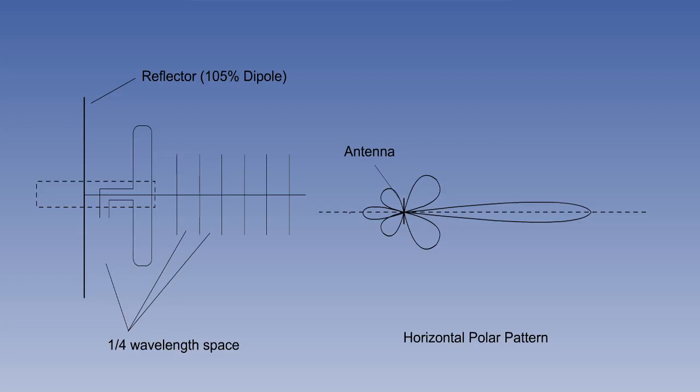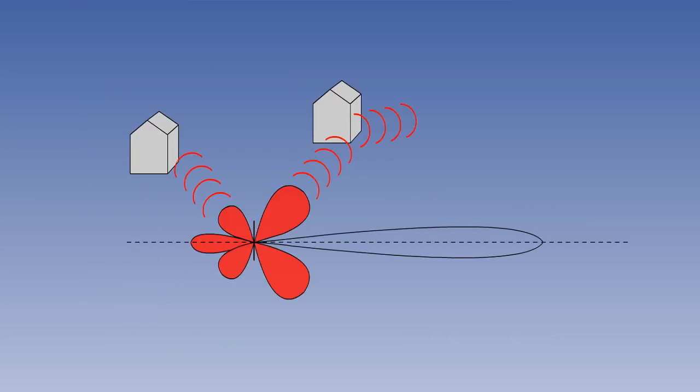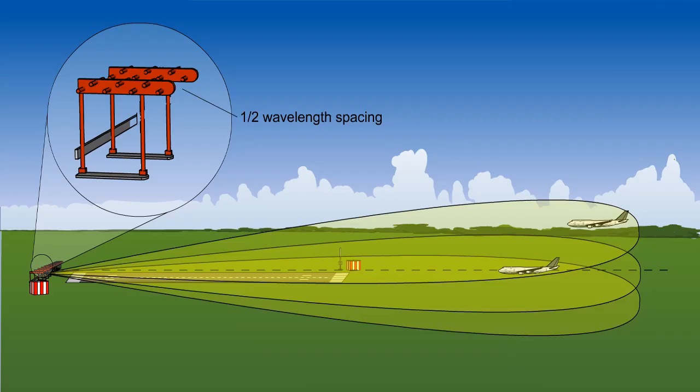They focus the signal out of or into the antenna, giving a stronger signal than that which would be generated by a simple dipole. These antennae are called Yagi antennae, and they are commonly used for televisions. However, directing a signal in this way produces side lobes, which transmit and receive unwanted signals, such as reflections from buildings. An application of the directed signal is the ILS.